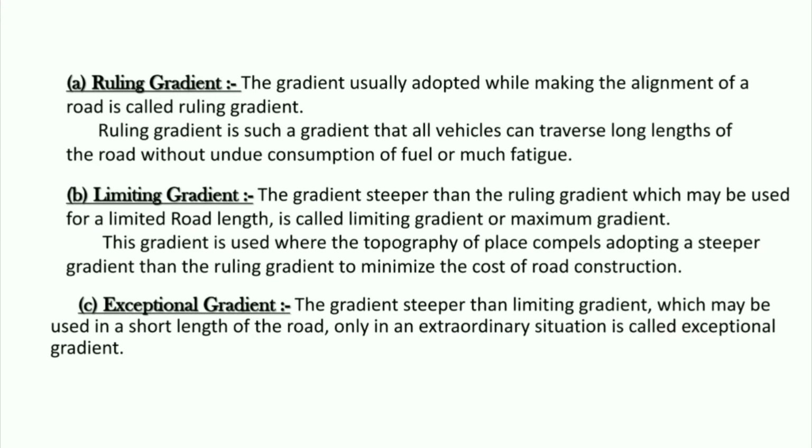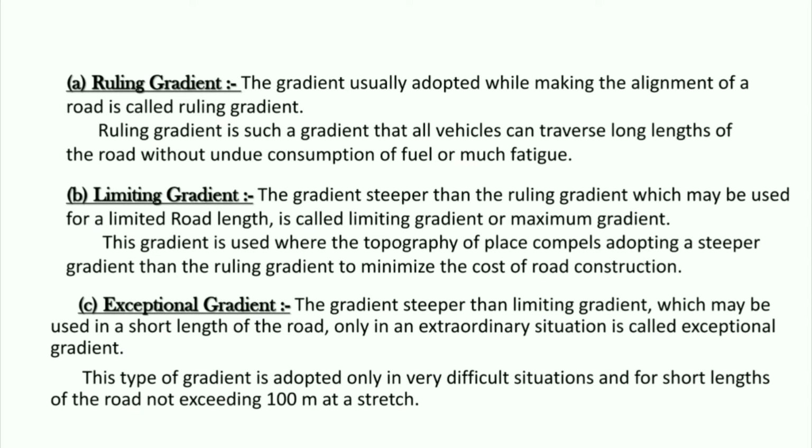Next is exceptional gradient. The gradient steeper than the limiting gradient, which may be used in a short length of road only in an extraordinary situation, is called exceptional gradient. This type of gradient is adopted only in very difficult situations and for short lengths not exceeding 100 meter at a stretch.